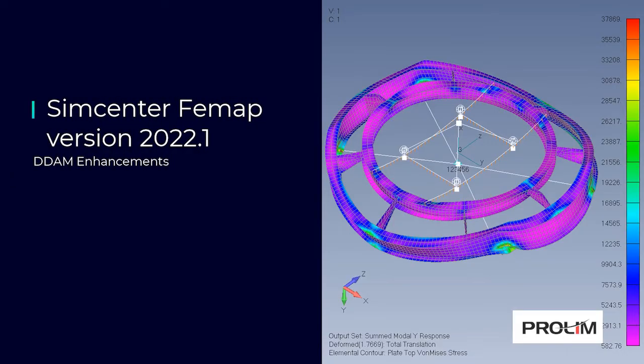Support for a new way to specify control options for the dynamic design analysis method, often called DDAM, has been added to Simcenter FEMAP 2022.1. DDAM is performed in 3 steps. First, Simcenter Nastran performs a modal analysis on the structure to calculate the modal participation factors and modal effective mass for each mode.